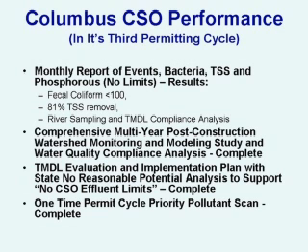In terms of Columbus CSO performance, there are monthly reports of events required by their NPDES permit, where they measure influent and effluent bacteria, TSS, and phosphorus, but there are no limits. There are no effluent limits on these permits. Back in the late 90s, we determined and demonstrated that there's no reasonable potential for the CSOs to exceed the water quality standards for bacteria, and therefore no permit limits were required. Fecal coliform levels are always under 100, and many times in the UV system they're below 10 colonies per 100 ml. Average removal for TSS is about 80%.